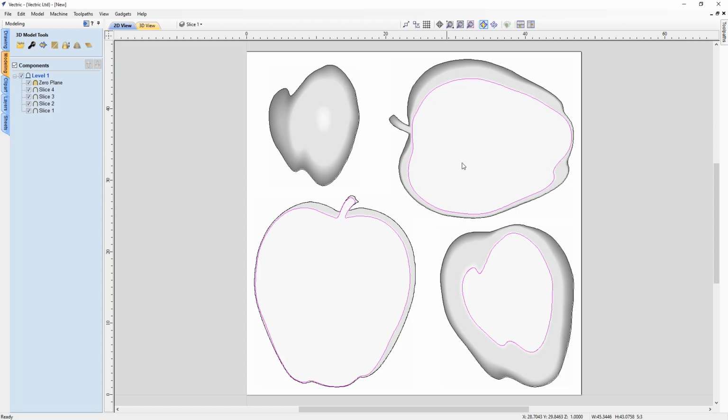We don't want to cut all of these flat areas with our 3D Toolpath. That would take a lot of extra time. We don't want to do that. Now also we're going to take this outside set of vectors and we're going to offset these out slightly so that when we do our 3D tooling, that finishing cutter will actually go off the edge of our model and end up giving us a nice clean edge all the way around and get all of our 3D detail that we want around the edges of these parts.